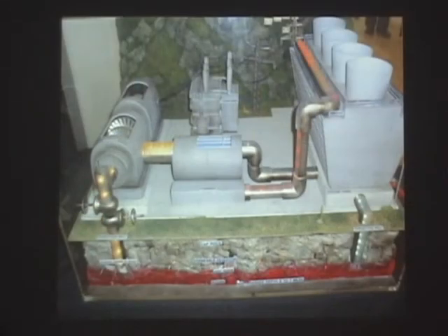This model, provided by Calpine, shows the use of a dry steam power plant to tap into the earth via a production well and through a reinjection well. The production wells at Calpine average about 8,500 feet, making their way through the upper cap rock, permeable reservoir, and into the lower hot rock. These production wells are then used to draw dry steam directly into a turbine, coupled with a generator, to produce electricity. The electricity makes its way through a transformer so that an appropriate voltage is maintained before it is delivered to the grid, making it accessible.